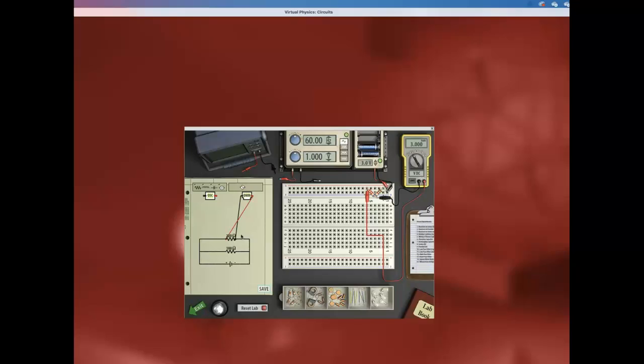Now after that we're going to go to the calculation section. In the calculation section, as I said, you are going to say series circuit, and then from step 5 calculate the average of the 3 current values. You have 3 current values, they should be ideally the same. You have measured all 3.